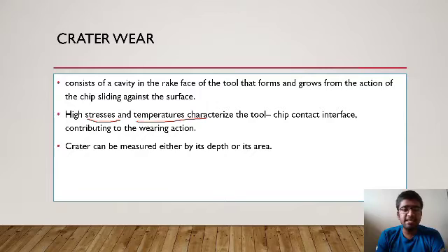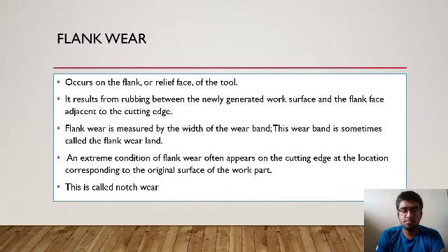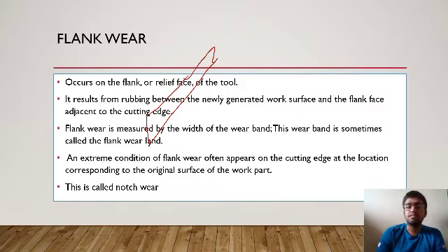The crater can be measured by either its depth or its area. Flank wear occurs at the side flank. Flank wear is predominant when we machine hard surfaces and at low speeds. Why is it so? Because at high speeds temperature is predominant and creates only crater wear.